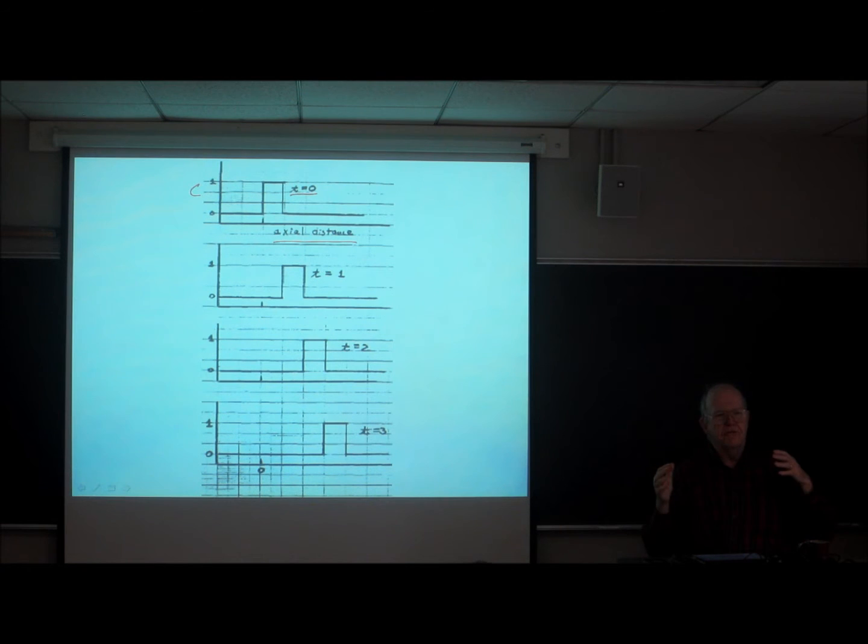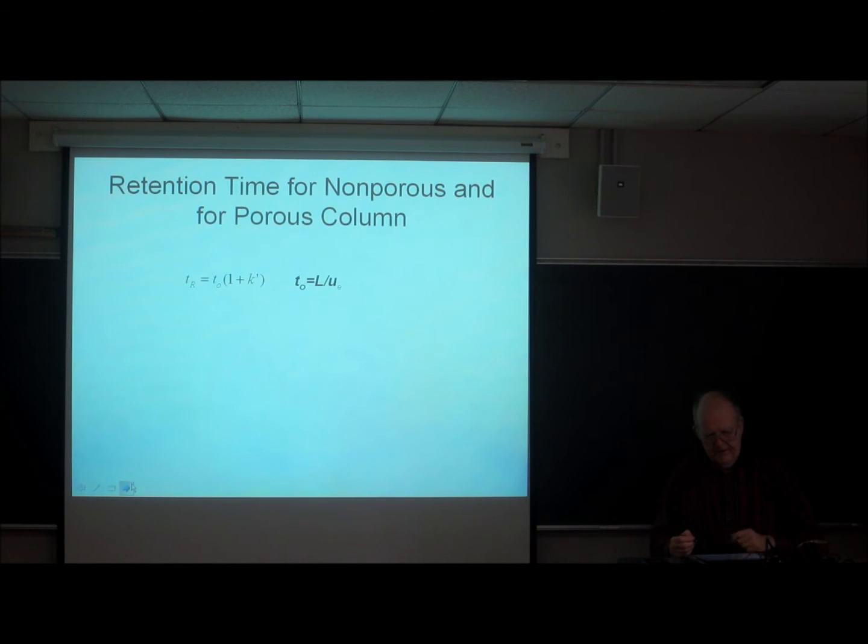We said that there is no axial diffusion, there's no axial eddy dispersion, and the solute remains in perfect equilibrium between the mobile and stationary phase. All of the broadening factors that we've been talking about have been taken out of the problem. So this is what absolutely has to happen. There is no broadening. You can easily show that that pulse is going to come out of the column at time tr.